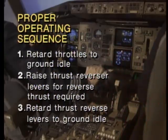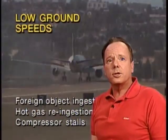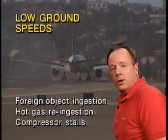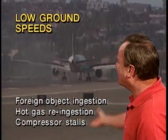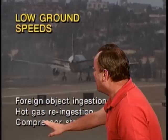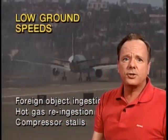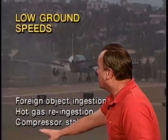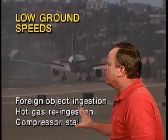Now, you can, in some cases, actually use reverse thrust to back the airplane up on the ground. It is not considered to be a good idea. It is, in fact, something to be done with great caution, because operating thrust reversers at low ground speeds can make you pick up sand and other foreign objects, so you can get foreign object ingestion. And also the hot gases can come back into the engine, so you have hot gas re-ingestion. That's considered to be a bad thing. And also the air from the exhaust gets up to the front of the engine and confuses the air at the front of the engine. That can cause compressor stall. So using reverse thrust on the ground is something to be done only with great caution.